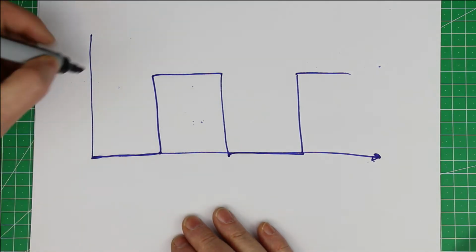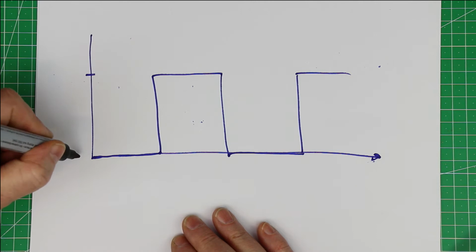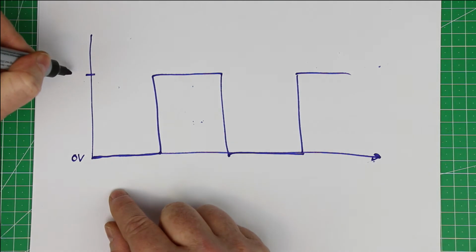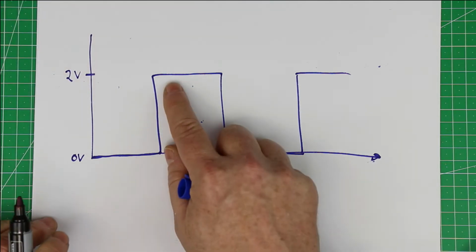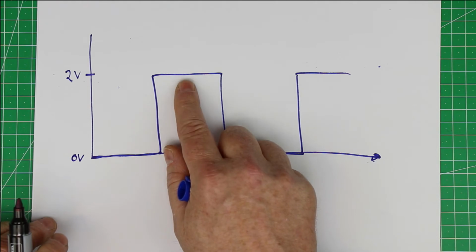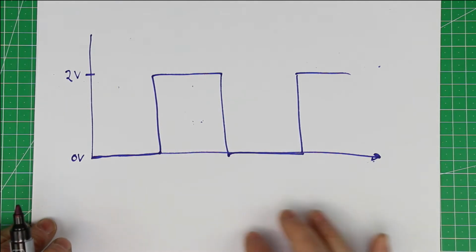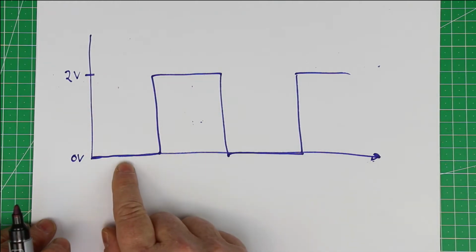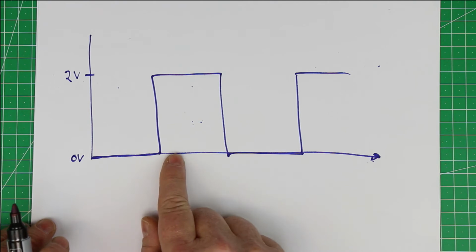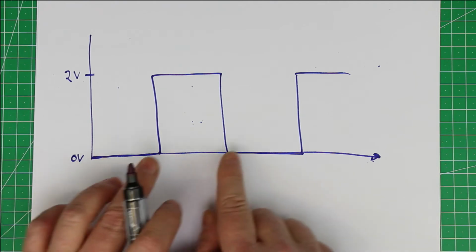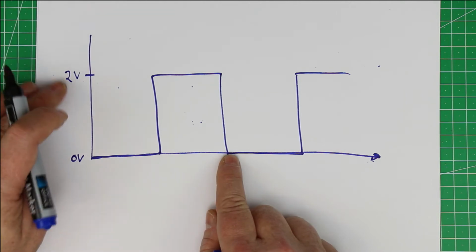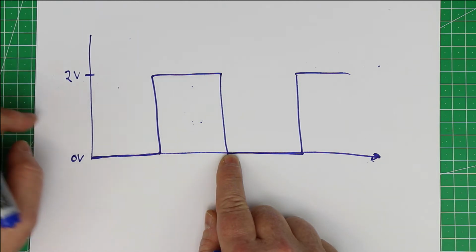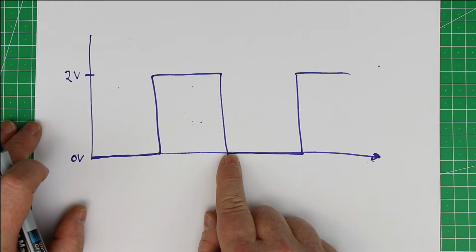And now let's presume the square wave starts at 0 volt and reaches a peak value in the on state of 2 volts. Now, what does your intuition say? What is the effective or RMS value of such a square wave? Well, you would suggest, well, it's half the time off, half the time with 2 volt, so it must be 1 volt RMS, 1 volt effective, right?